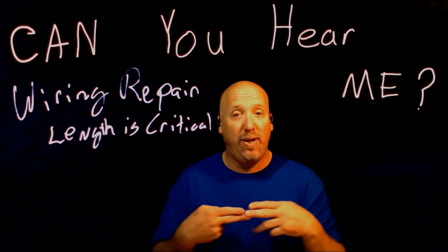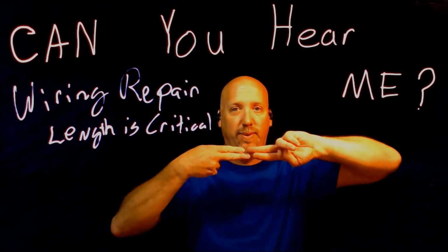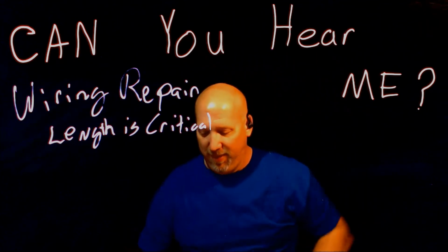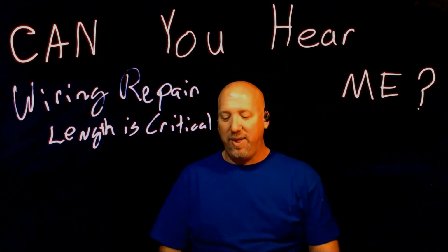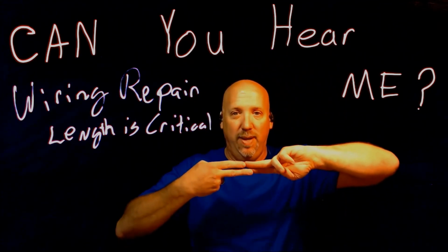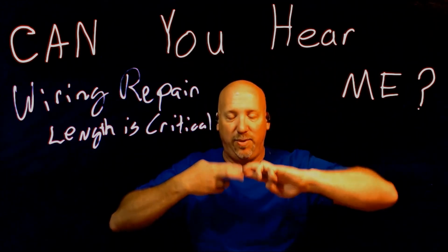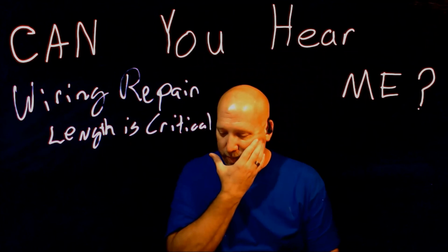If splicing a pair of wires, 2 wires together, you don't splice them like this, again, splicing like that. When splicing a pair of wires, offset the splices to allow for better twisting. Keep your splices away from each other. Put them together, you're not going to have a twist there. So offset them for better twisting.